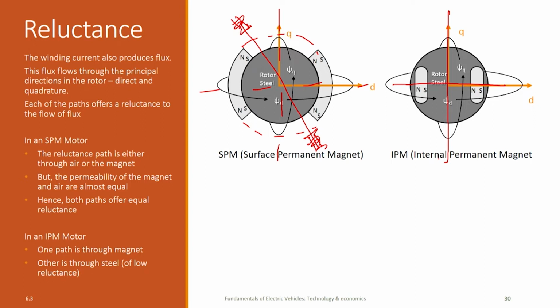the q axis, and we already know that the reciprocal of reluctance is called permeance, and permeance multiplied by n squared is commonly called, all of this we studied in the first chapter on flux. 1 by reluctance is the permeance, and when we multiply permeance by the square of the number of turns, n squared, it is called the inductance. And where the reluctance is low, inductance will be higher because they are reciprocally related.